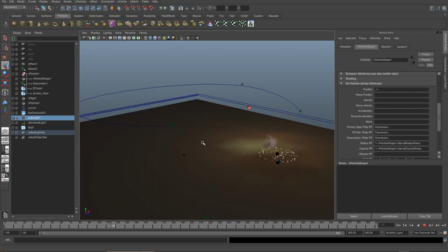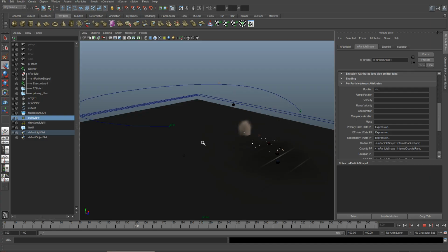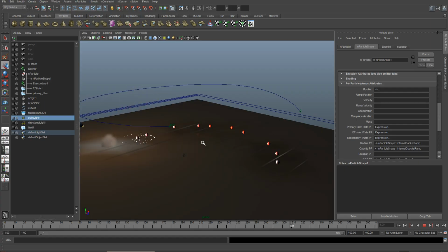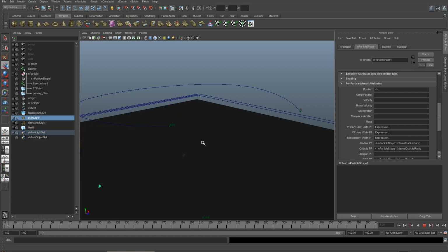Okay, I'm going to call this part quits. We've added some density to the scene. In the next part we're going to look at adding both temperature and fuel to get the actual explosion. We're going to look at shading this density as well, which we'll be using as the smoke cloud, so it gets darker as it explodes and then fades away to lighter. And we will be concentrating on purely fluid shading within the next part. So I will now take a quick 400 frame render of this, and I will show you in the next part where we are so far. So thanks for watching, and see you soon.